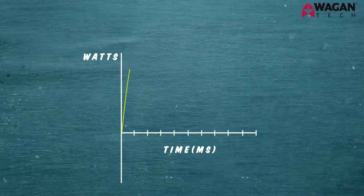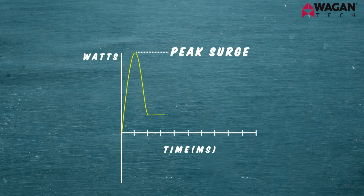Lastly, let's talk about peak surge. You may have heard of it before and been wondering what it means. What it is: when a high wattage device starts up, it draws an insane amount of power for usually less than 1/2 of a second. That's called the peak surge of the device. Some devices can surge up to 3 times the amount of its running wattage. This is something you need to take a look at when selecting an appropriate inverter for your needs.